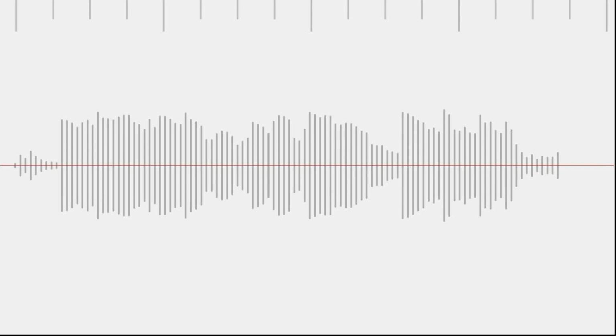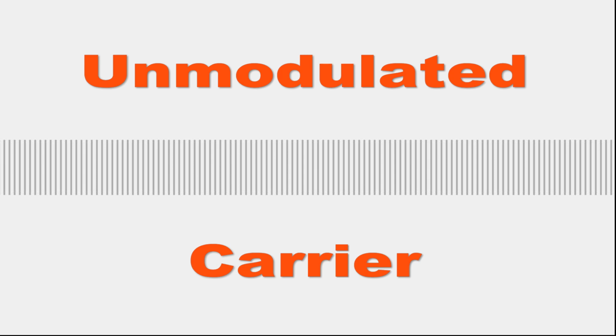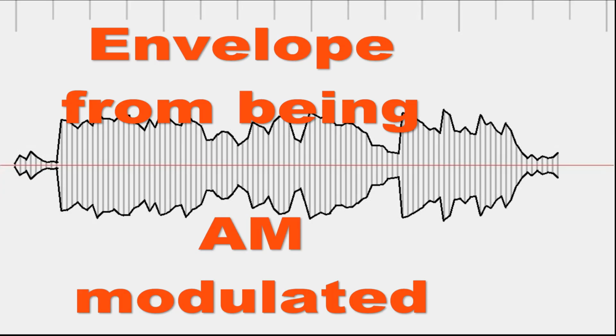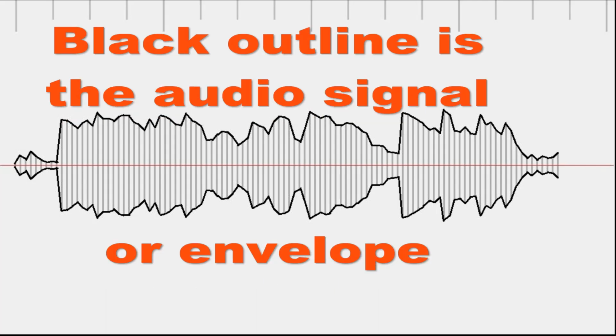An unmodulated signal from a transmitter can be displayed like this. It's called a carrier and is uniform across its spectrum. When you modulate a signal in a transmitter, you use a mixer of some sort and superimpose the signal on the carrier, the signal meaning the audio, which would be sound or music.